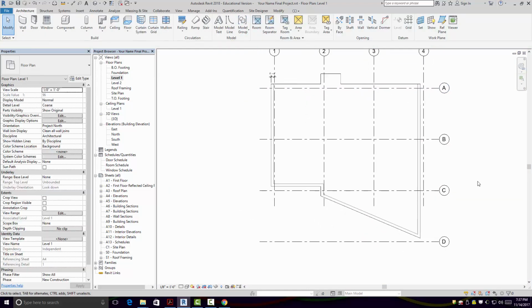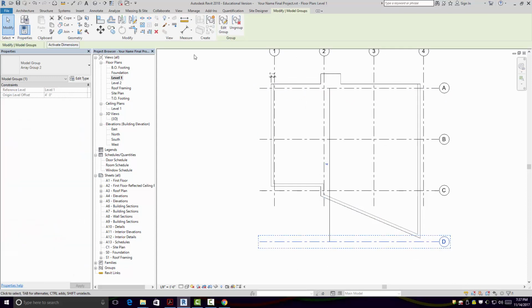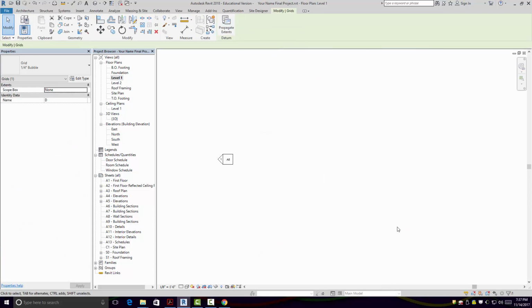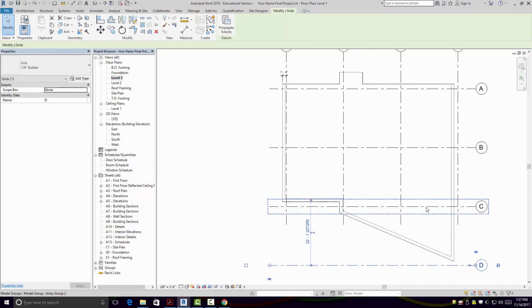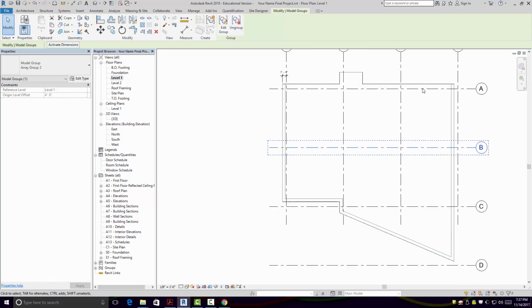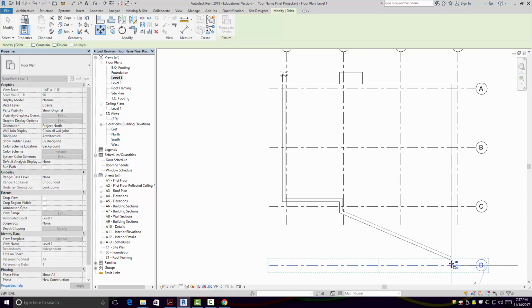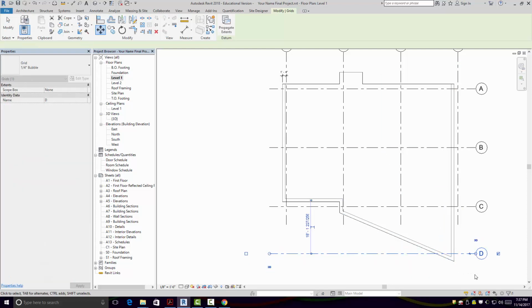But if I want to just totally depart from the group, like D, I want D to be up here, I'm just going to go ahead and ungroup it. Say ungroup right here. And right now, all those are as if I had copied them. Actually, you're still part of the group. But this one, I can actually move. So let's say I have 1 column here.